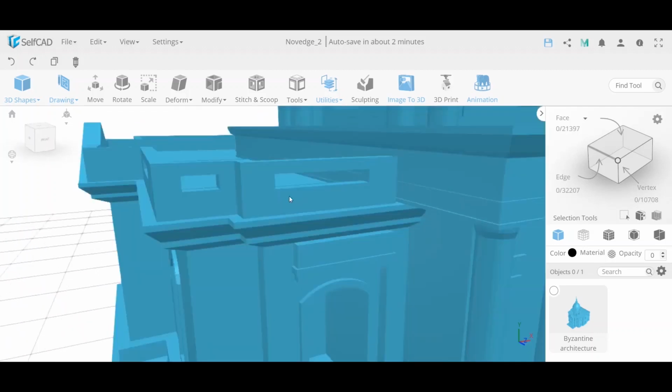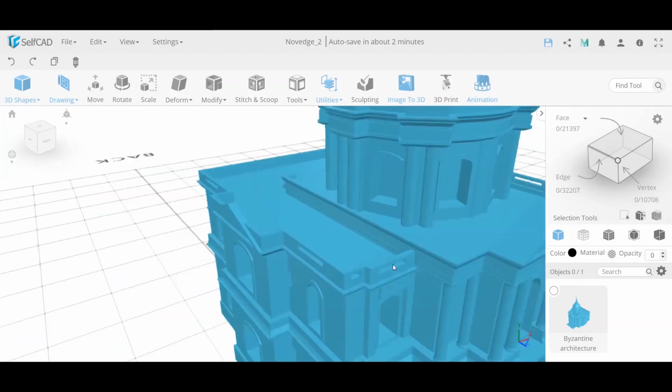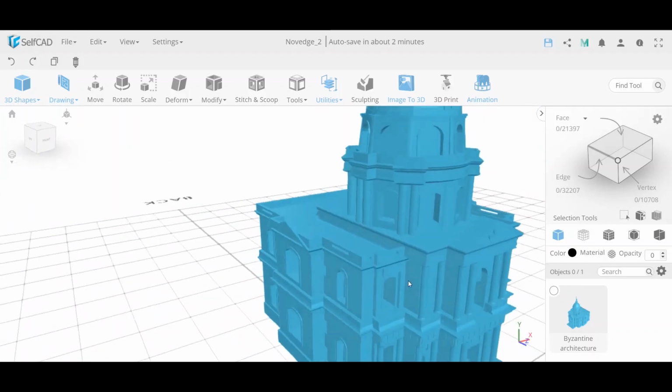In this case, you do see holes over here, and that's understandable because a normal Boolean cuts out of a volume. Considering the entire building is one volume, if you cut into it, you just cut out a part from it and it stays solid. Whereas if you cut through the entire thing, say the windows on the other side are perpendicular and you put something the thickness of the entire building, it will make a hole. So in this case, it created a hole. So how can you actually make holes in a building like this?